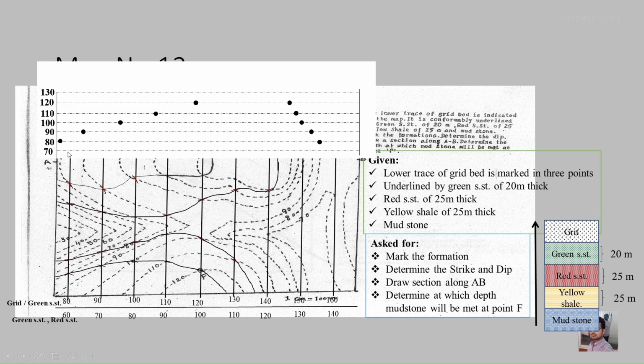Now we have to connect these dots and make the profile line. As you can see, it starts from 80 to 90, an uptrend, so we can start the profile line below 80. We draw a line from 80 to 90, then 100, then 110, then 120. There is no 130 contour, so you have to take a U-turn from here towards here without touching the top line.